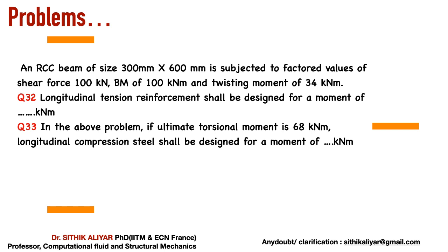So an RCC beam of size 300 into 600 mm is subject to a factored value of shear force 100, bending moment 100 and twisting moment 34. So they are asking for the longitudinal tension steel, so they are asking Mu1, okay. That is question number 32, and in question number 33, they have changed the moment from 34 to 68. They are asking what is the moment to be designed for Me2, they are asking for the compression steel, okay.